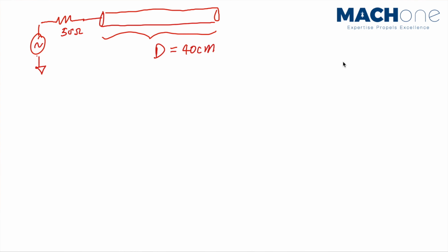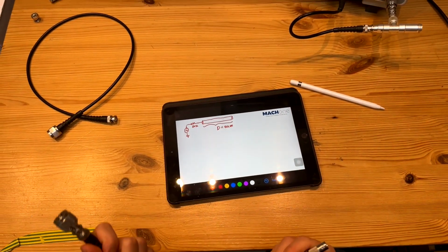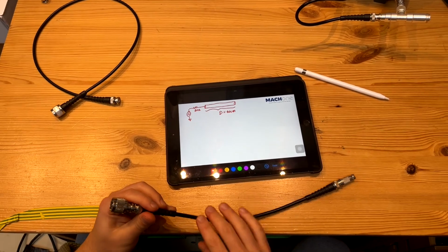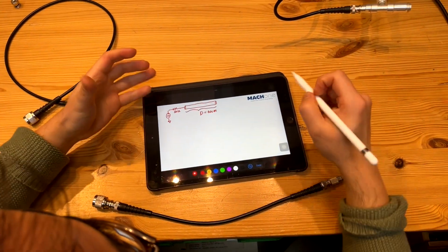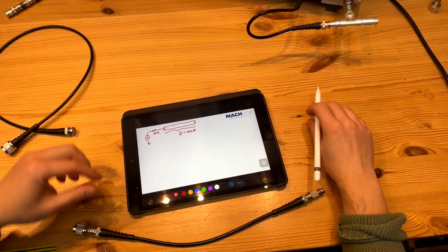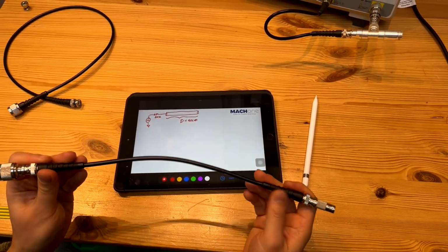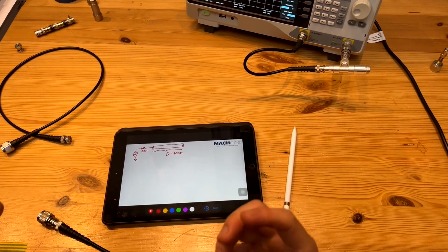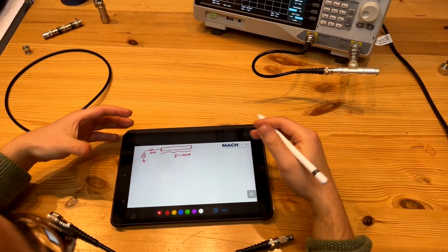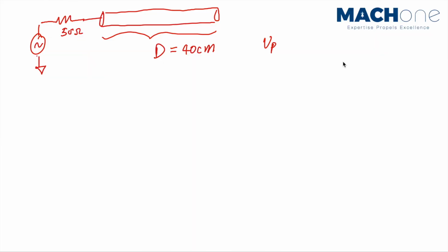And we know that when we send signals or power using a cable structure like this, there really is wave action inside this coaxial cable. And the wave, we said, travels close to the speed of light. But because of the way we build this coaxial cable, the relative permittivity and permeability determine the velocity of propagation, which we call VP, and it is slower than the speed of light.